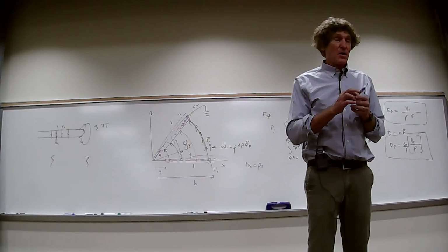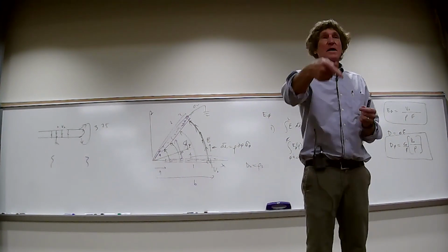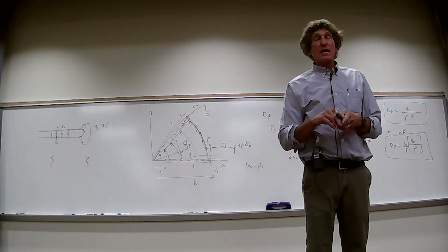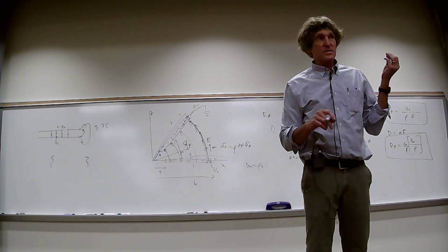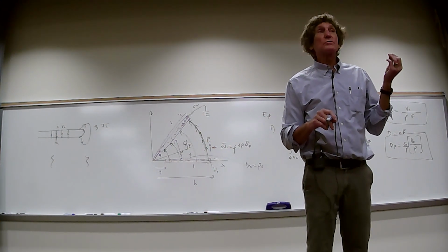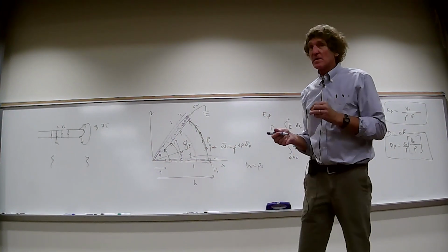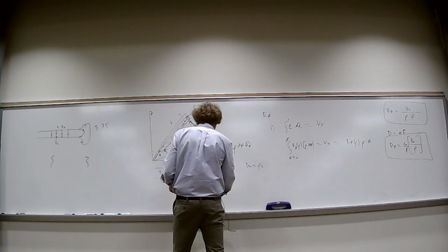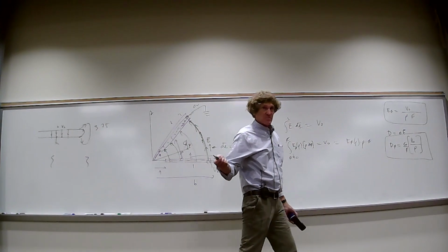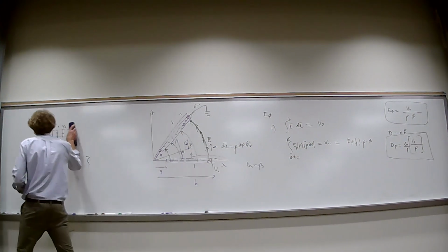Do y'all follow this? Now, we did this backward. We started assuming the voltage, then we got the E field, a little trickier. Then we got the D field, and then if we evaluate the D field on the surfaces of either plate, we get the charge density, right? We're almost there. We need the total charge on one plate to get the capacitance still. Y'all follow me on this? What's going to be the total charge on one plate? If we have the D field as the charge density, we'll do this per meter too, right? I think they want capacitance per meter, I assume. Let's do that over here. This is a great problem.